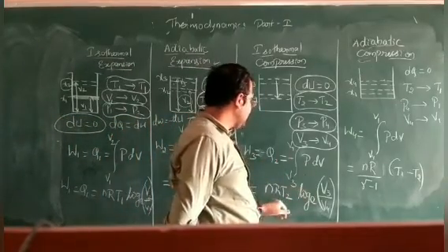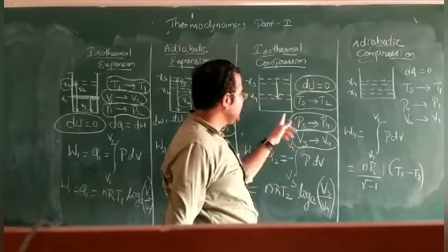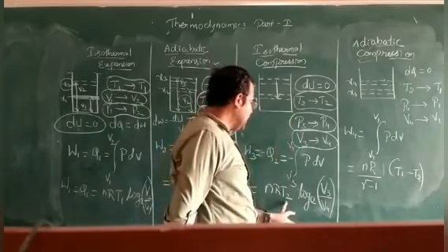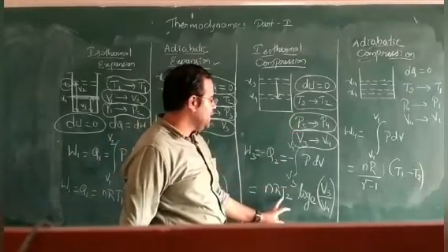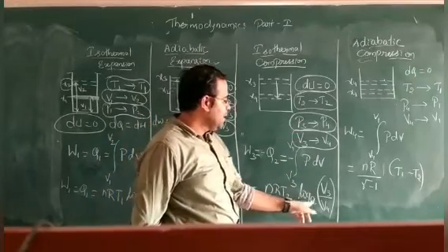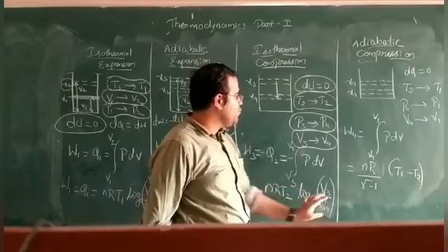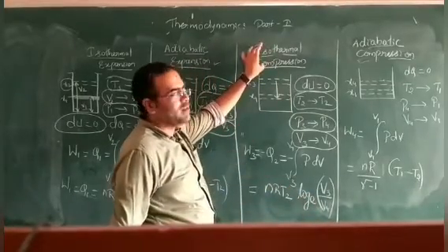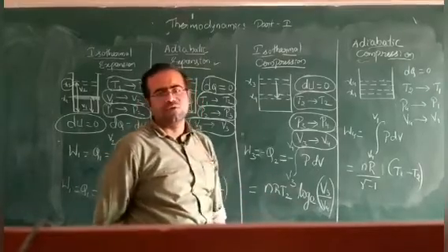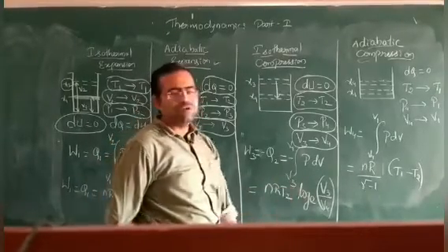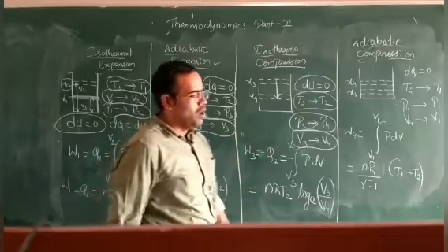So again the equation nR. Now the temperature in this process, what temperature do you observe? In the third step the temperature is T2, so here you write T2. So T2 multiplied by log of e to the V3 divided by V4. Because it is isothermal, the work done in isothermal process equation is already derived in the previous content. So the same equation you are writing according to the volumes here.